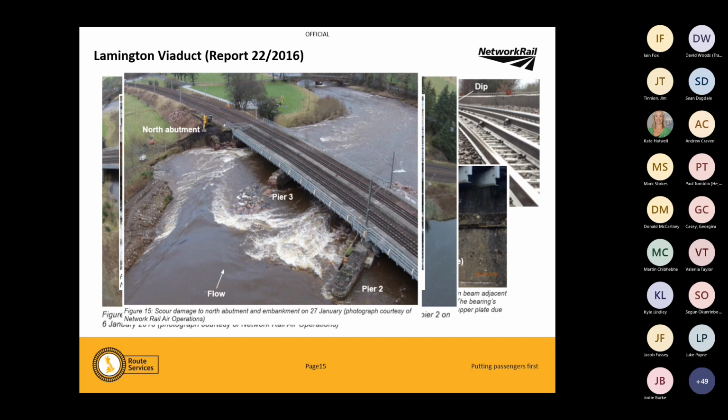And what they've done is create this lovely pontoon, I guess, to get the excavator out, so we can create a dry working area so that we can work around pier 2. That's great. However, as all of you now know on the call, because you've been listening intently, I'm sure, what have we done with this channel now? We've gone from that width to this width, Q equals VA. We've now increased the velocity through these parts of the structure.